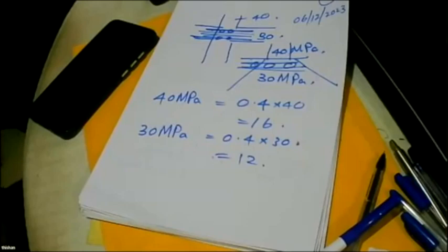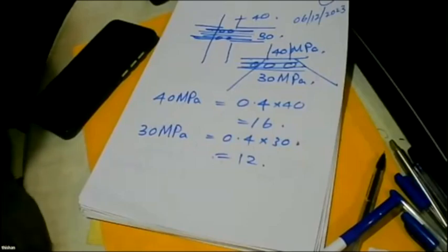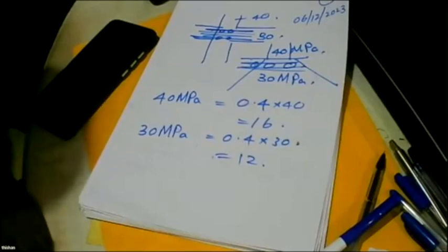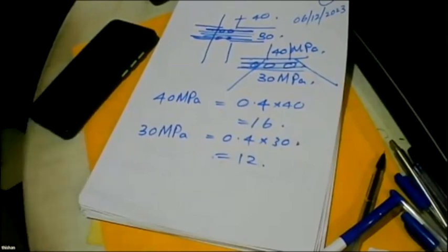You can do pile rafts only in areas having very good laterite soil, where the bedrock is deep, where you are going to stop the piles in the laterite soil as friction piles. Otherwise, if you are having end bearing piles, going for a pile raft is wrong.